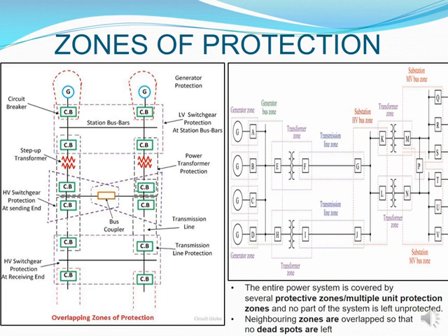Okay, then between your transformer zones and your substation HV bus zone that I just mentioned, you also have your transmission line in there, and you can see that at the end of each transmission line there are 2 circuit breakers that are protecting it again. And so it goes. Once you've reached your substation HV bus zone, you go again into these distribution transformers, where again you've got your circuit breaker at either side of those.